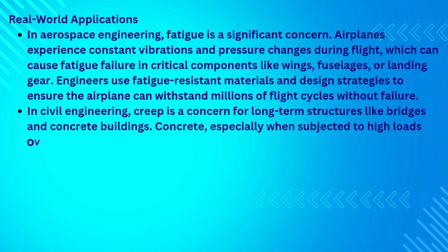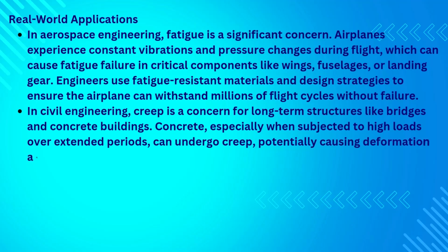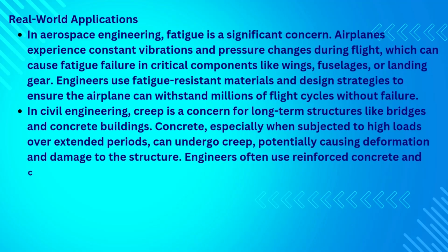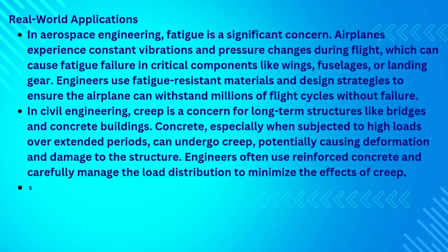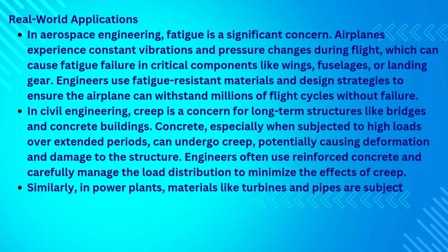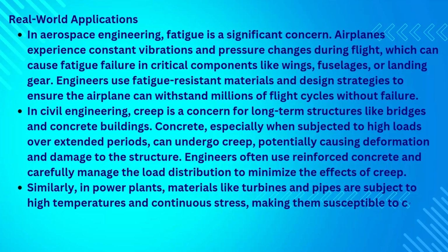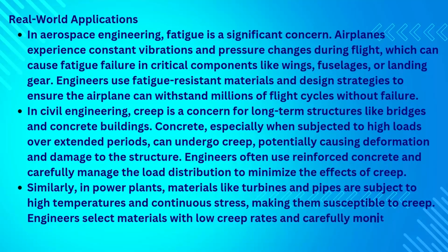Concrete, especially when subjected to high loads over extended periods, can undergo creep, potentially causing deformation and damage to the structure. Engineers often use reinforced concrete and carefully manage the load distribution to minimize the effects of creep. Similarly, in power plants, materials like turbines and pipes are subject to high temperatures and continuous stress, making them susceptible to creep. Engineers select materials with low creep rates and carefully monitor their performance to avoid failure.